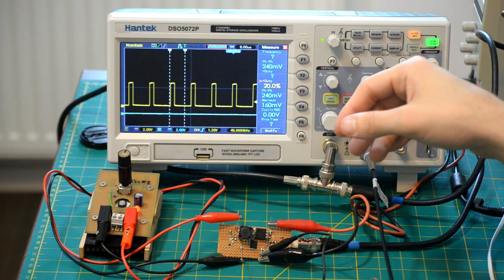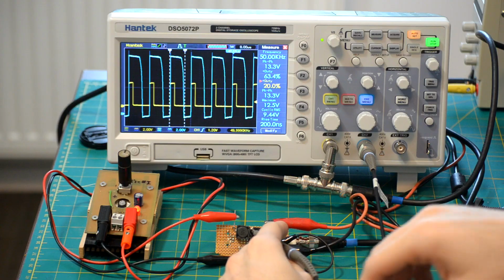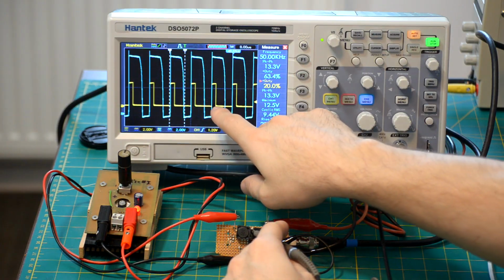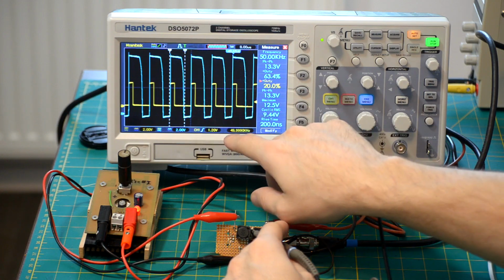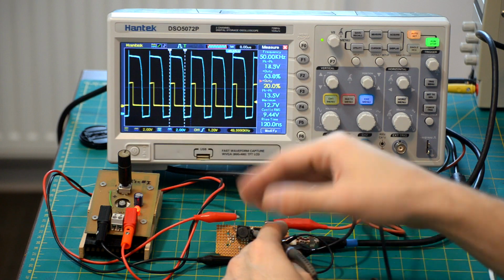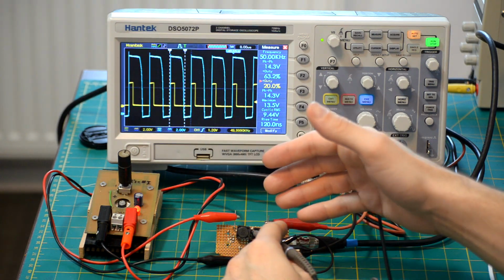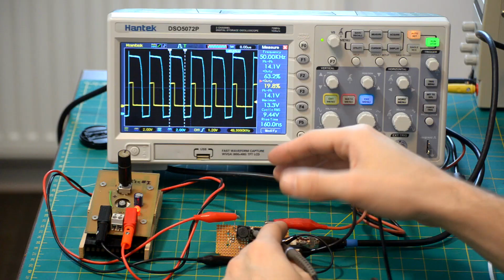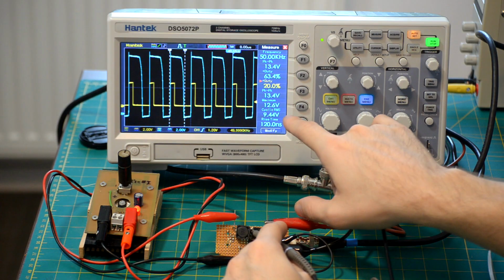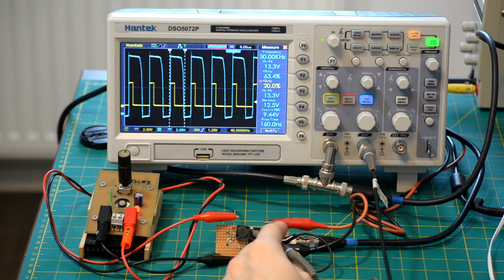Now we can take the oscilloscope probe and look at what the switching node looks like in real life. We can see, just like in our simulation, that when the input signal is high, so is the voltage in the switching node, and then they both turn low. But we see one more thing, which we shouldn't be seeing. There's quite a lot of delay in between the two signals. And this ends up affecting the duty cycle. Even though I'm driving the circuit with a 20% duty cycle, I end up having 63% because of this delay.